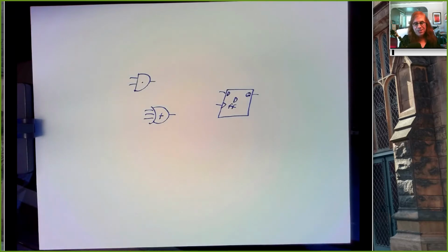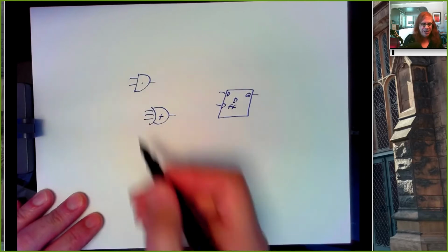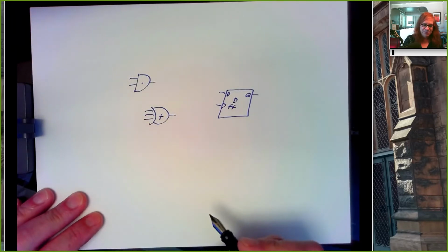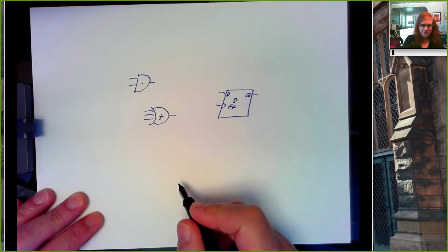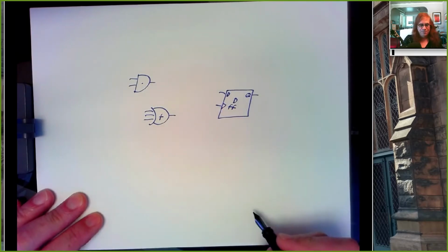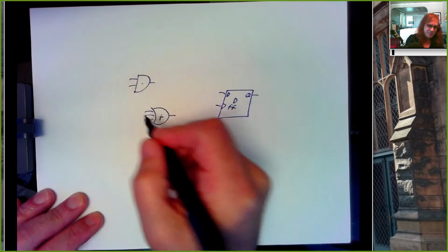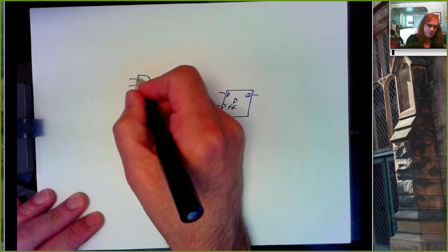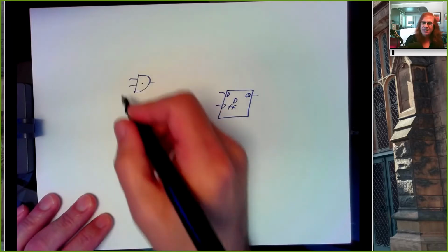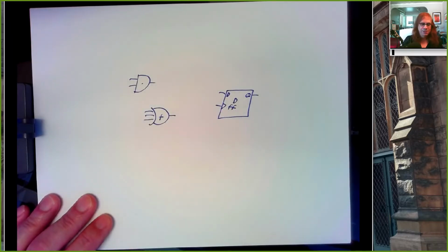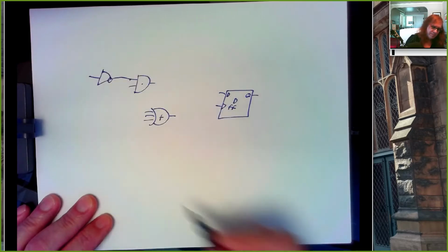So you make your logic diagram using logic symbols for standard blocks like AND, OR, NOT, and so on and so forth. If I want my output to be inverted, right, make an inverter. If I want to take the complement of Q and connect that to this input, don't just draw a little circle here, because we don't have a physical device that's a 2-input AND gate with 1 input inverted, right? Make an inverter.